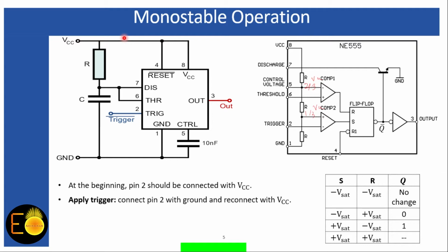Now think about your sensor, say a smoke sensor that generates a signal against the detection of smoke if present within your room. That signal may be continuous over time, it can stay for a while, but your trigger must be a negative edge trigger.